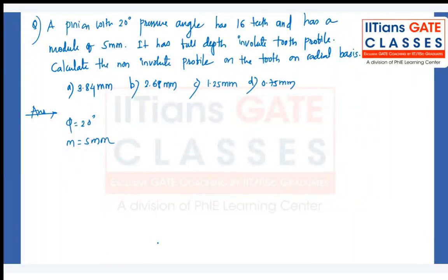It has a full depth involute tooth profile. So you can use the standard value of the addendum and the dedendum, considering the complete value of the addendum and dedendum, and proceed with the solution.